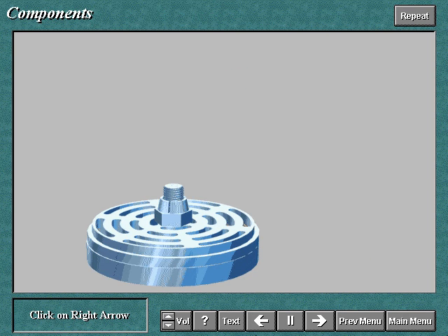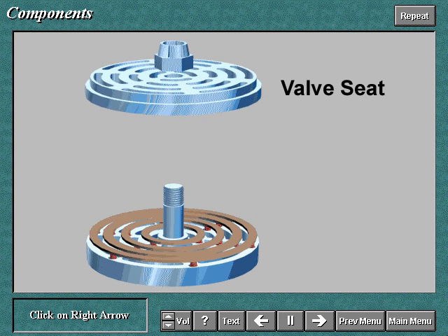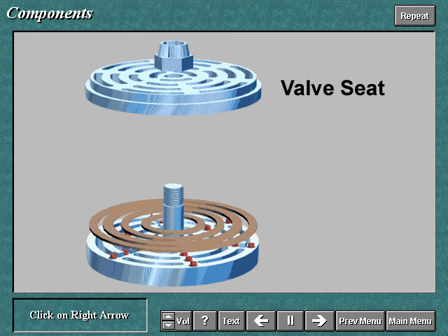All valves used on reciprocating compressors are made up of 4 basic elements: the valve seat, valve plate, springs, and valve stop. The valve seat is the circular component through which the flow ports are opened. It is sealed by the valve shutter. The seat and valve shutter together mechanically support the pressure differential. The seats are mounted in housings arranged along the body of the cylinder.